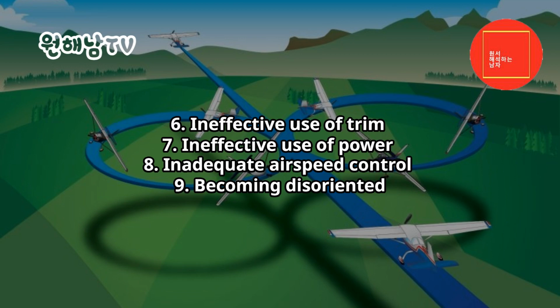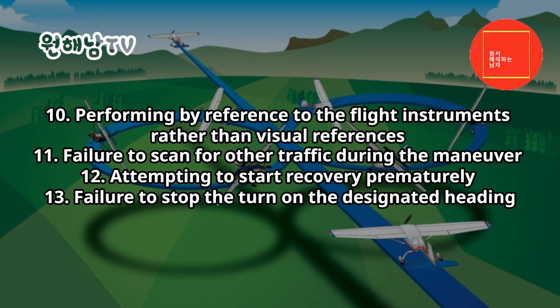8. Inadequate airspeed control. 9. Becoming disoriented. 10. Performing by reference to the flight instruments rather than visual references. 11. Failure to scan for other traffic during the maneuver. 12. Attempting to start recovery prematurely. 13. Failure to stop the turn on the designated heading.